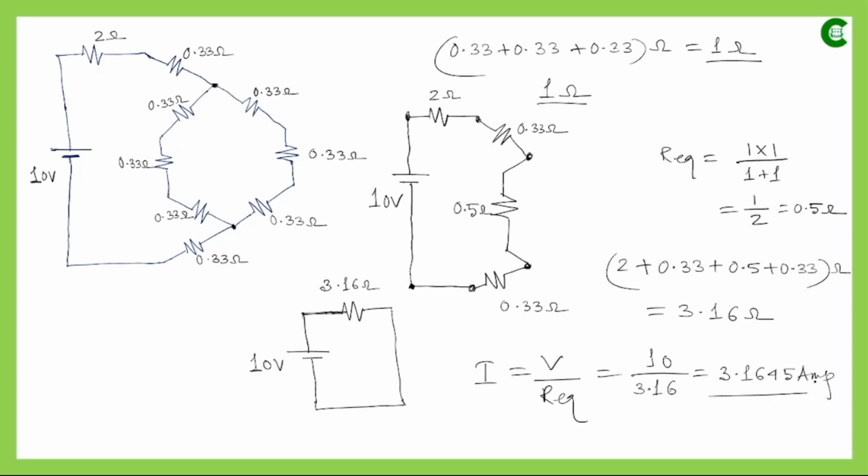So this is the way in an electrical circuit where we need to simplify a circuit which has several elements, maybe DC components, maybe AC components, but we need to simplify, and we see that if three components are connected in star, but if they were connected in delta, then it would have been easier for us to simplify. This way we can use the concept of star-delta or delta-star connection, and we can easily simplify that circuit. So this is the end of the class.